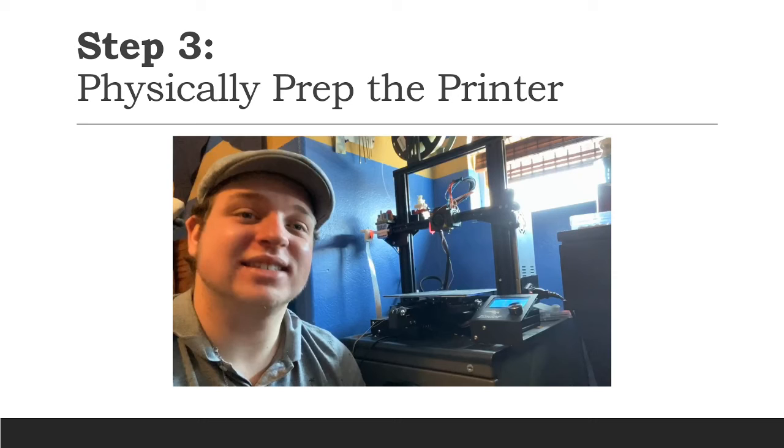So all you're going to have to do is upload, and then make sure you select your G code and not your STL file. It's going to upload real quick here, nice and easy, and then all you have to do is click, and it'll pop up here, and then you have to hit print. And that's all you have to do for this step.